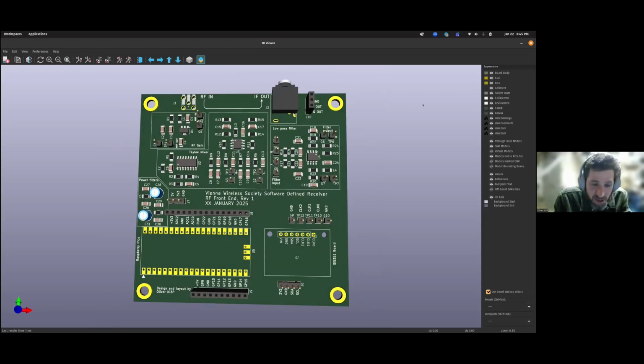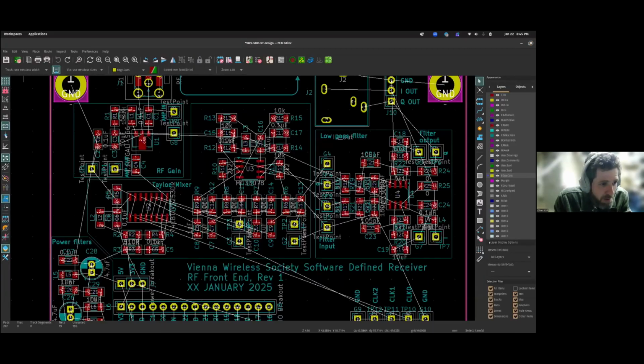So the next step is routing. As someone pointed out earlier, it's a good practice to have 50 ohm traces, so at least your trace impedance of your little transmission lines on your board don't cause discontinuities. In reality, this is an HF board. The physical size of this is a few inches. It is a very tiny fraction of a wavelength. So if you're hand waving these things, the trace impedance doesn't really matter if the physical thing is that small.